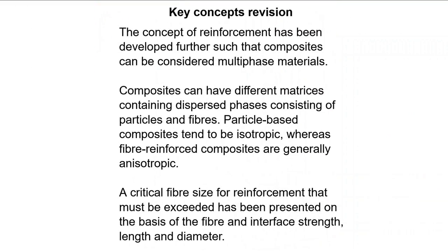So in this part of the lecture, we've described composites in a broad sense, not on the basis inferred by the term reinforcement, but on the basis that all properties beyond mechanical ones can be changed by including a different material class or family. We've also described the breakdown of composites extending from being long, continuously reinforced materials back to particulate reinforcing ones on the basis of fiber efficiency.